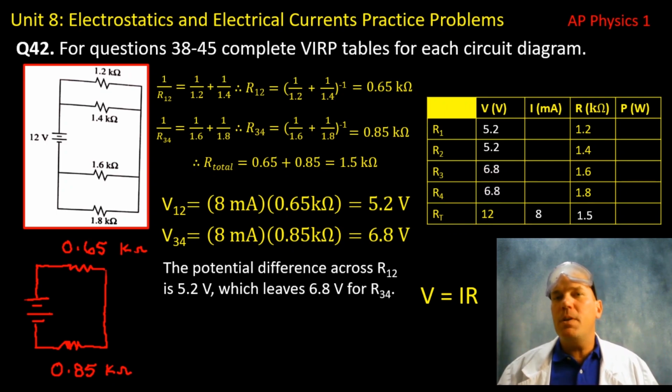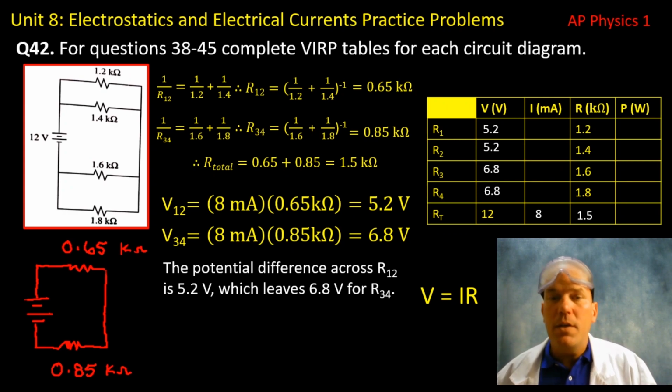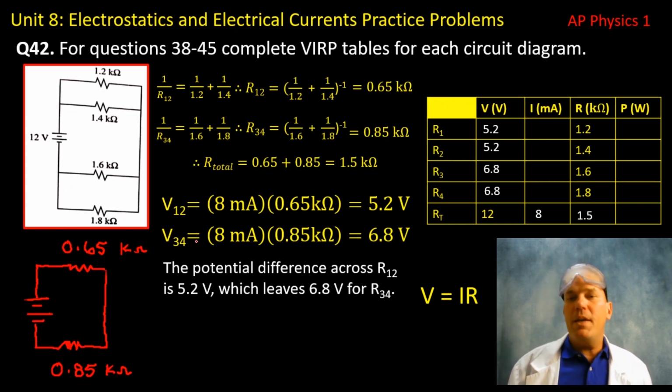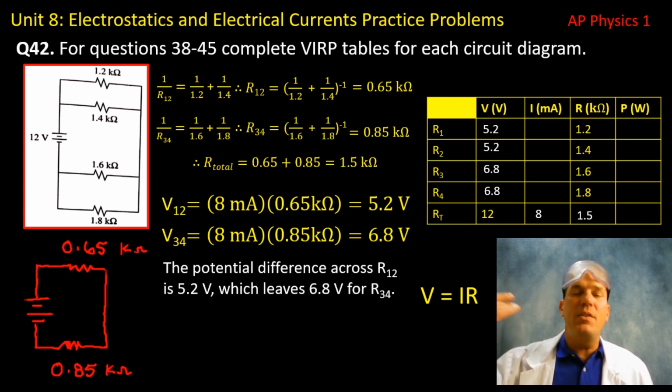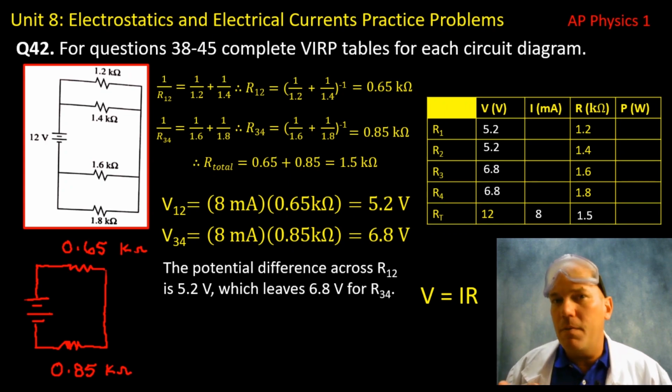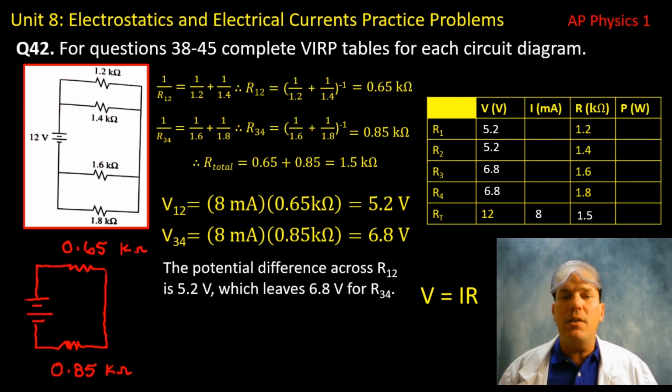and say there's a 5.2 potential difference across both R1, R2, then 12 minus 5.2, or using Ohm's law, like we did right here, either way works, we can then get a potential difference of 6.8. So you can either say, okay, 12 minus 5.2 is 6.8, or if you have time and you're really sitting down to think about this, do both ways. As I've explained here, if they support one another, 6.8 and 6.8, then you know that you've done this correctly.